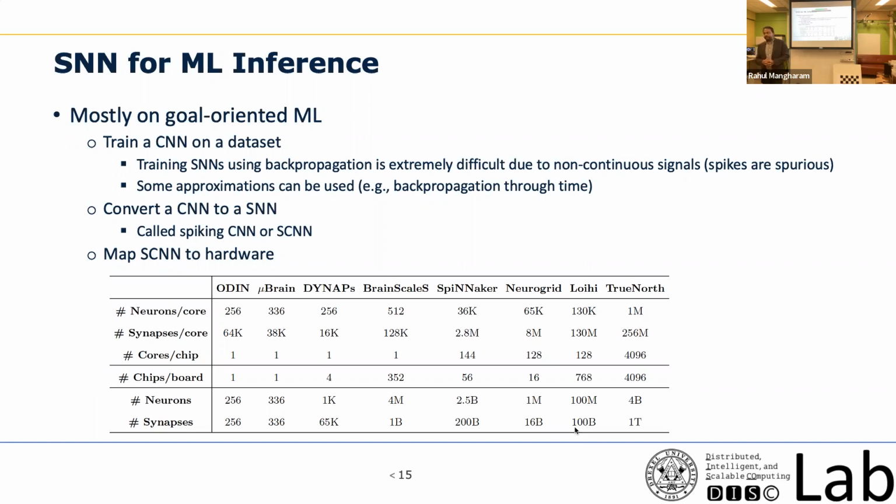Okay, so it's an ASIC, not an FPGA? It is ASIC and FPGA. You can do it on FPGA, and I will show you some results on that. But it's not an FPGA in the sense that you can't reconfigure the connections at runtime. No. But the good part is how neural networks are clustered and mapped. You can implement many different architectures, many different CNNs, skip connections, everything, on those hardware, even though the actual static hardware doesn't support it.